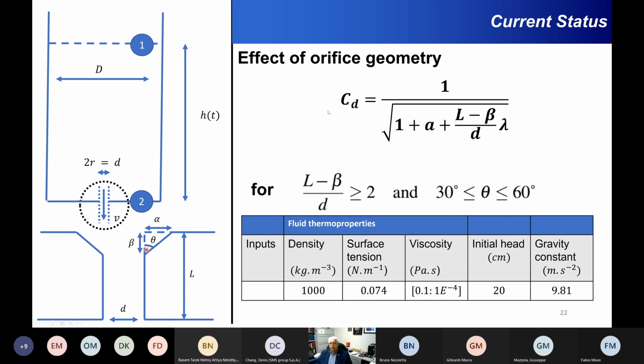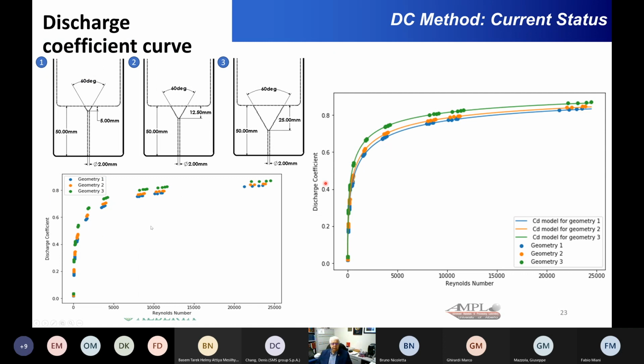And you can see here we can express the viscous losses as a function of those parameters. And we can basically control those parameters through machining to be within certain ranges. We put in a set of parameters. We've been doing experiments with water, for example, and we can see here that we're looking at experiments versus a model that uses those parameters.